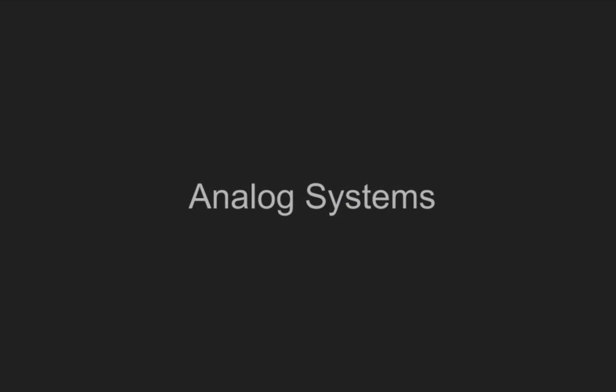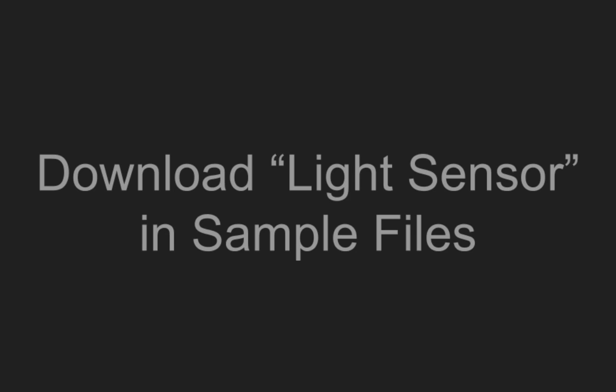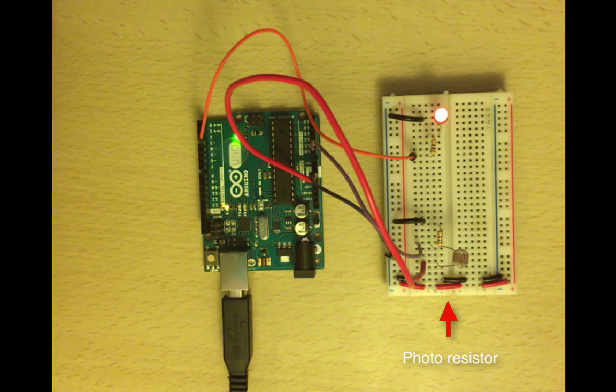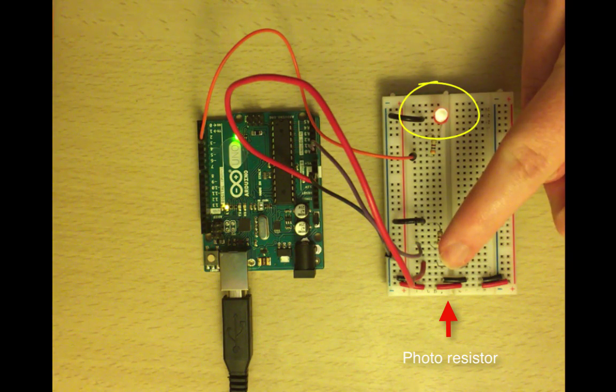Analog system. Copy the setup on your own board. Remember that the short end of the LED should always go to ground. Download and open the sample file titled Light Sensor. Once you have everything set up on your board, plug in your USB cable to the computer. Upload the code. Try covering the photoresistor and see how the light values change accordingly.